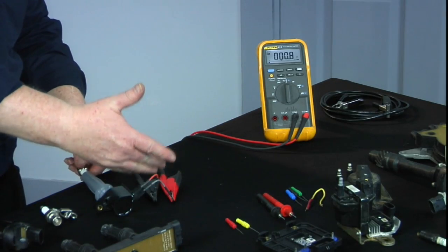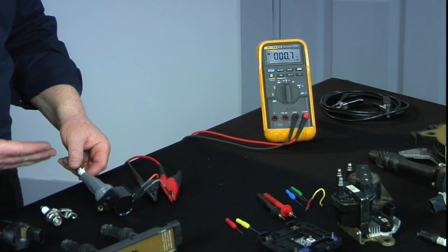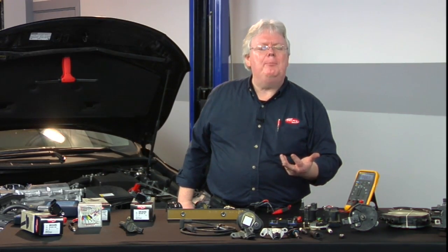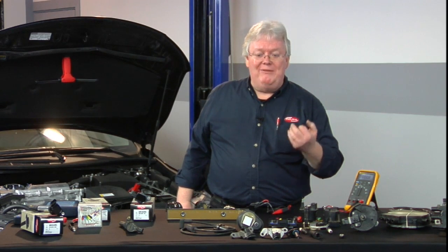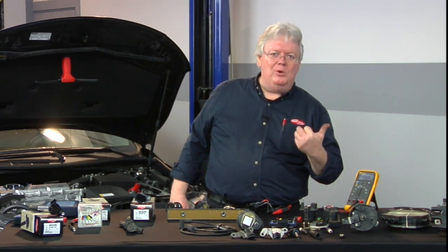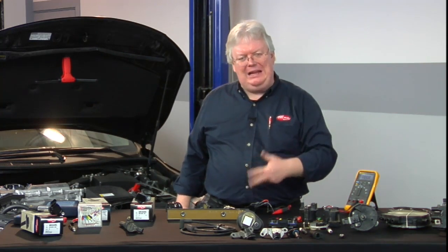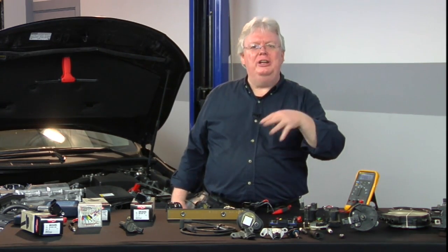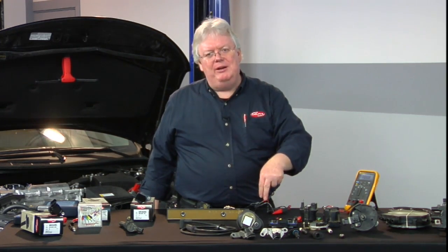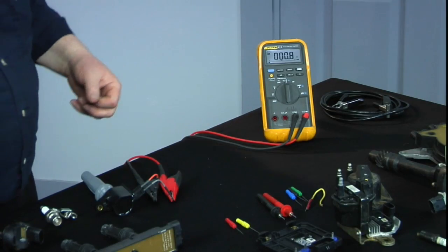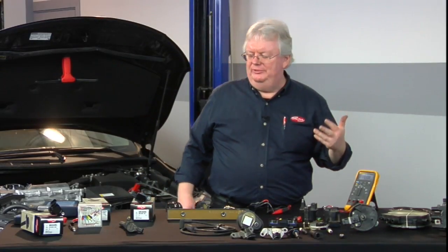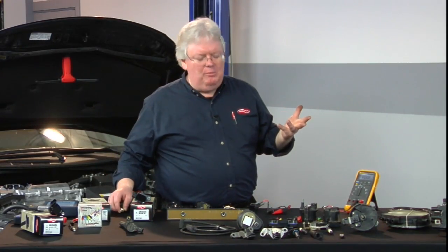But up top, where the harness plugs in for each individual coil, we're going to have two wires. One's going to be the ignition feed. The other one's going to be providing a ground whenever that coil needs to turn on, saturate that primary winding, and then turn off, of course. That's when the spark occurs in the secondary, the self-induction turning into the mutual induction. And that's what we can measure on the primary right now, with a couple jumper leads, and we're seeing about 0.8, so that's a little less than 20 amps.